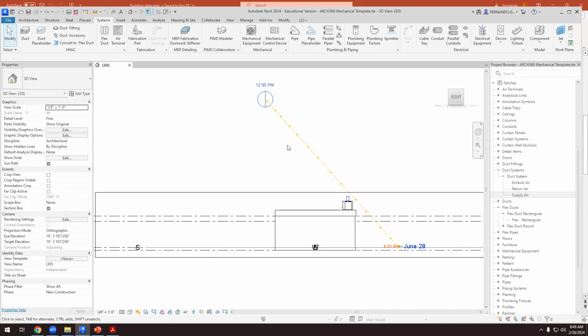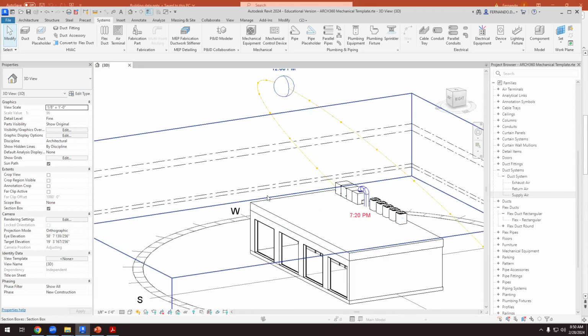So we have to make a decision, and that's why it depends on the location. It depends on the latitude. We are in the Northeast, the United States. So something around 40 goes well. If we have a tilt of 40 degrees, it works. Like that's the roof, and that's the PV panel. Something between 30 and 45 degrees will work with this angle. Okay, so that's what we're going to do. We're going to place PV panels there.